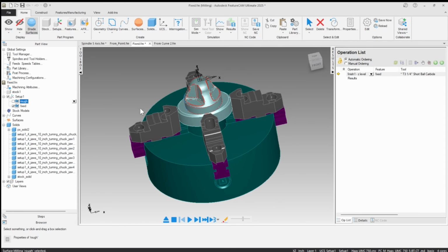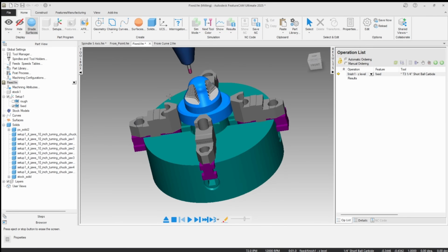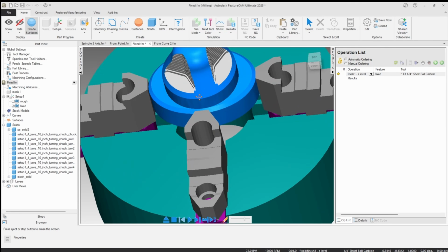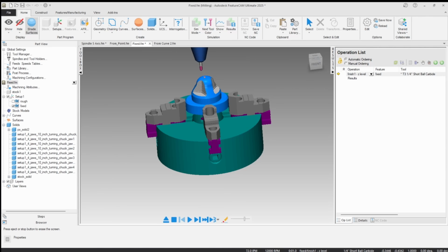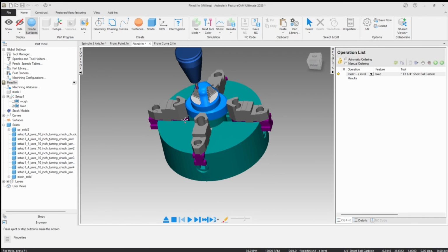So this has been roughed out in these openings all the way around. Let me go ahead and just single step this in 3D for you. You'll see that it's been roughed out, and I took the result of the simulation so that it starts at that point. And so what I want to do is tilt this tool on one angle, because I'm only going to machine this area in this example. So you see I have a gouge right away, right?